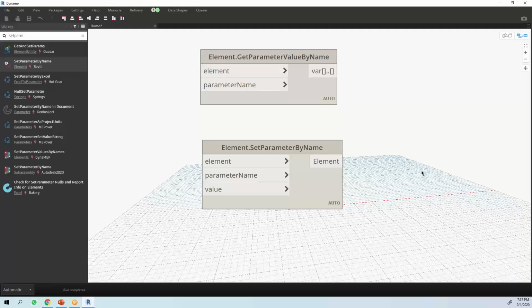Are they in different locations on different floors, or the same location? No, those are not typical. Okay, let's consider it's typical. If I model one floor, then it's possible to copy paste. But will they exactly host to those particular floors? I mean, if it is for the slabs or for the ceilings, will they be placed exactly on those ceilings if you copy them? No, right? It's just a copy. Still, they are orphans. If there is a change in the ceiling, then how do you change it?